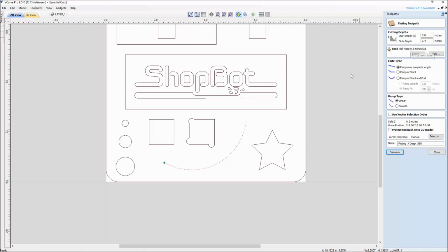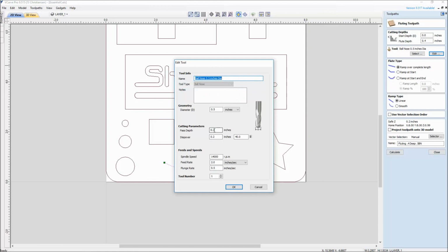that I'm using. Just to point out here in the software, when you are doing a fluting toolpath, even though you have your start point here with the green dot, the plunging of the cut has to do with how many passes you're going to have. It's a little bit complicated to throw out for the first one, but right now I have a 0.4 flute depth and a pass depth of 0.2. Being that this is a 0.4 cut with a 0.2 pass, it's going to do it in 2 passes. That's an even number of passes.